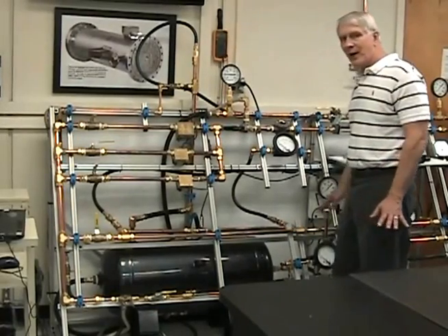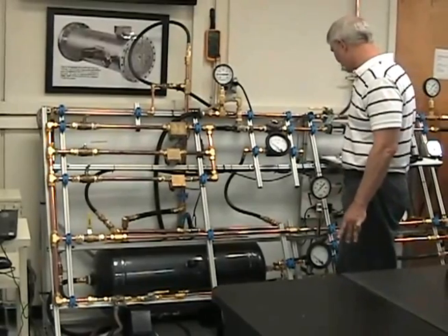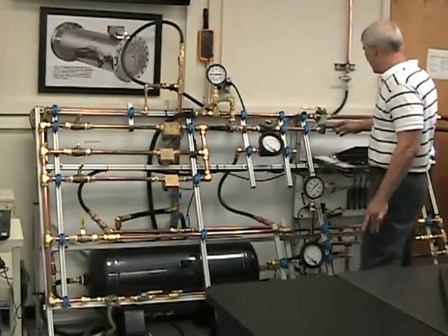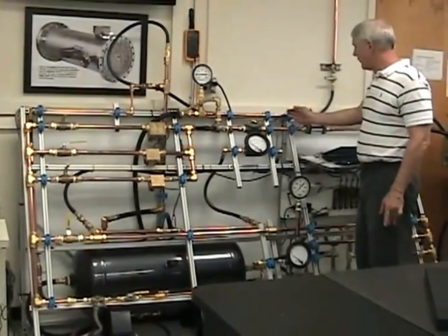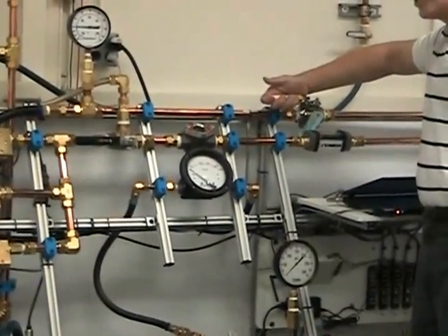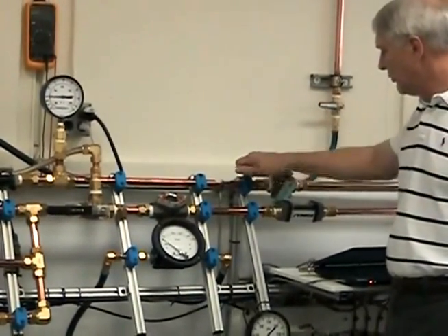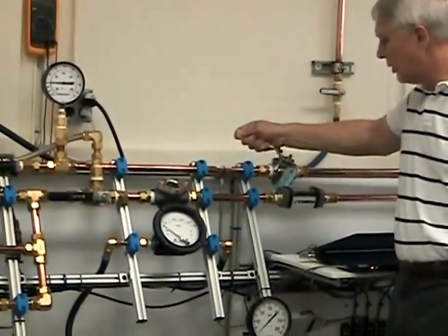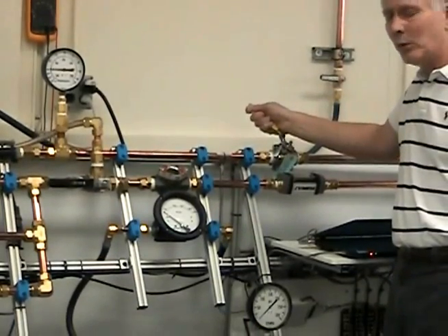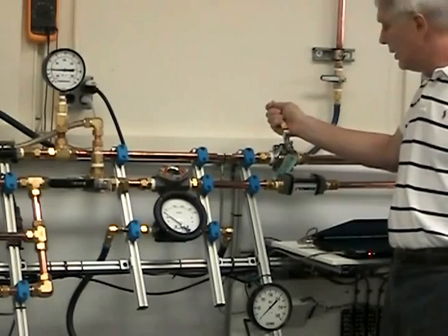Okay, there are other valves on here, but they're only used for maintenance, so you don't have to worry about those except for one of them. In order to control the flow, we have a valve up here that's labeled the control valve. And so right now it's wide open, so we have the maximum flow. If we want to reduce the flow, we just turn it like this, and then you adjust it to whatever flow rate you want until it's ultimately all the way closed like that.